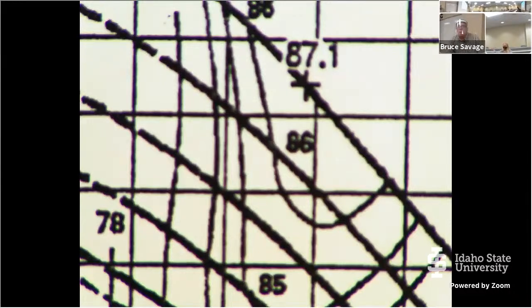Then it's a judgment call of, do I need the higher flow rate? If I need the higher flow rate, go with the bigger one. But if you don't need the higher flow rate, the concept is this: if I'm going to pick the higher one, but then I'm going to stick a valve on my system that constantly has to burn that additional energy up, I haven't really gained anything, right?